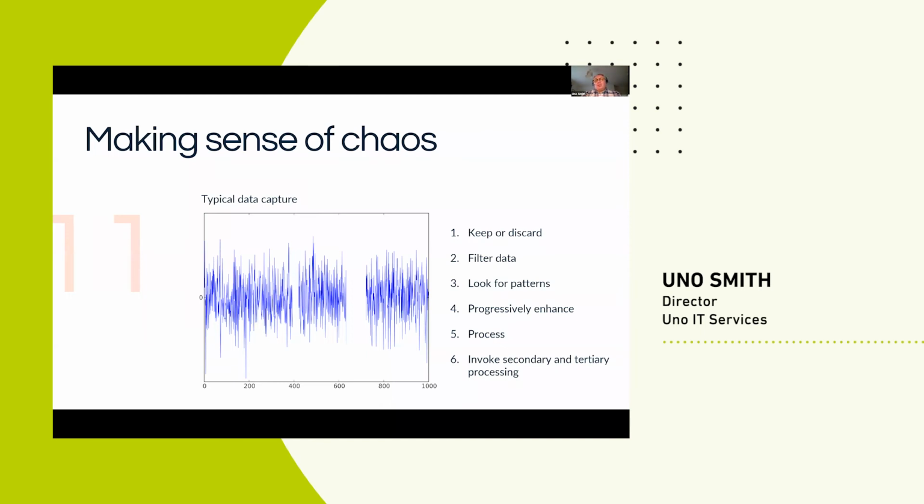Once you start getting information, it's worth looking at how you can combine one or two data streams that have already been filtered, because you may apply a filter to take out the noise in a data stream like this, but that has its own artifacts often.